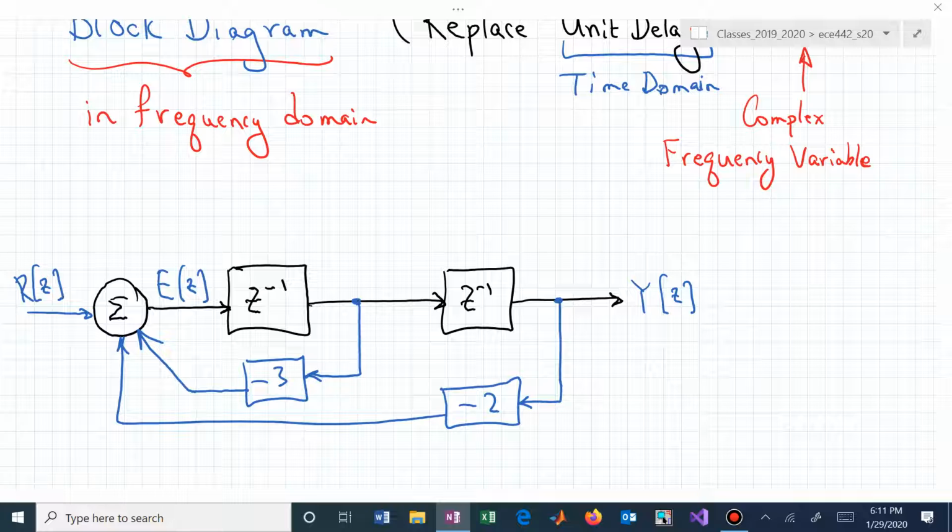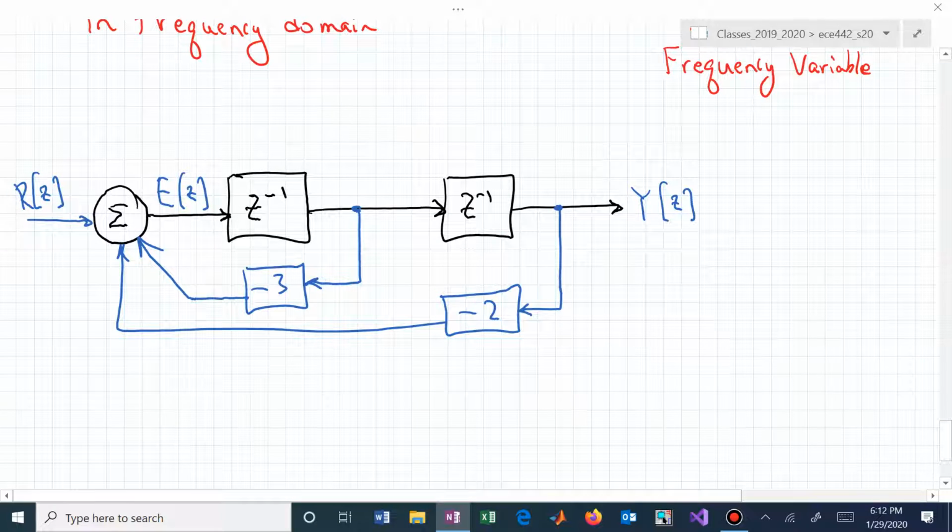We can't say 6 apples are equal to 5 apples plus an orange. That doesn't work. We have to be consistent on both sides of the equality sign. We have to be working with apples on both sides, or signals on both sides. And to produce maybe a little bit more straightforward analysis in this block diagram algebra, it's usually helpful to write your equations based on the output signals from summing junctions.